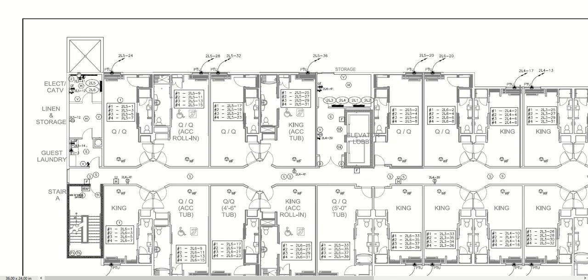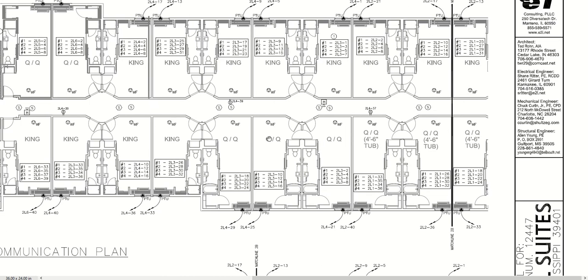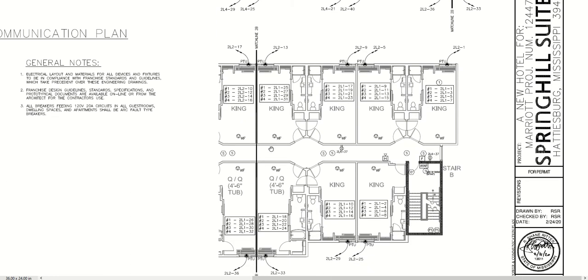Here's one of the electrical rooms, again stacked on top of the main electrical room, so that's pretty convenient. We do have a washer and dryer here, so you see a dryer special connection and then an outlet just for the washer, and then the circuits per room like we talked about before. They did give us another electrical room on each floor here in the middle, and that helps with voltage drop because we didn't want to run our circuits the entire length. So this gives us a medium point there. We stuck 4 more panels in these middles. They're really storage closets, but we're using them as storage/electrical rooms, which is okay as long as they don't put stuff in front of it.